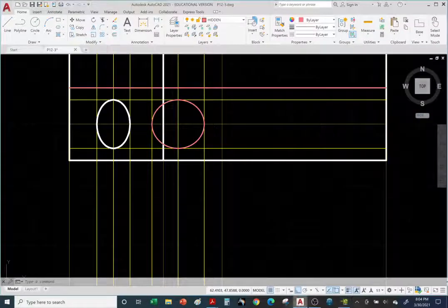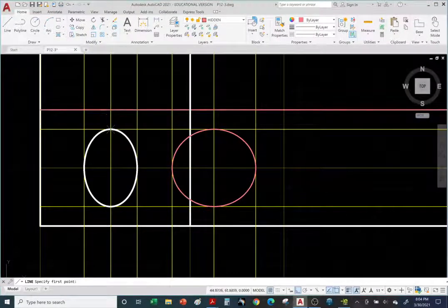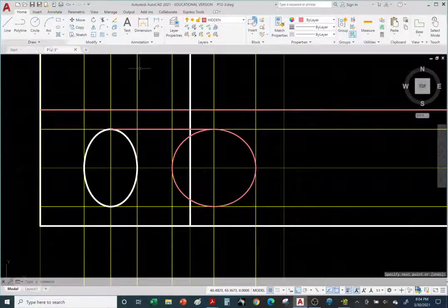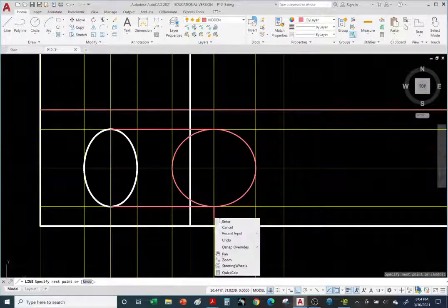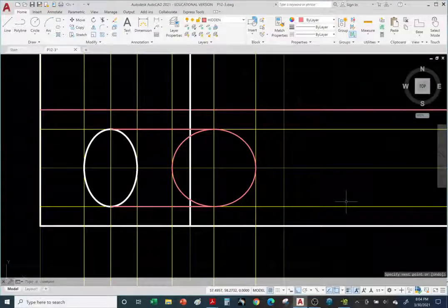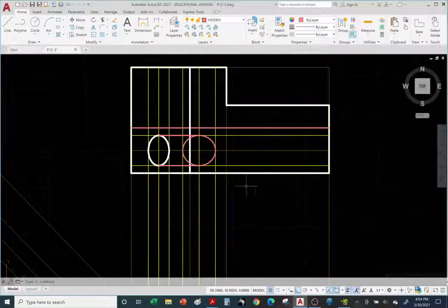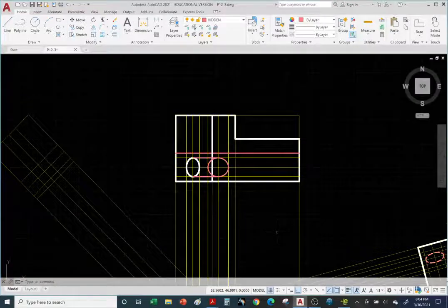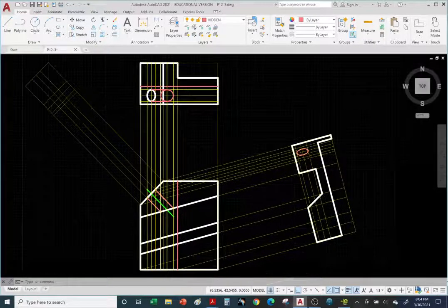All right, back to AutoCAD. Let's connect the ellipses with red hidden lines. They're hidden because we can't see them. Right-click Enter. Okay, and bottom quadrant, and right-click Enter, and there we have it. Ta-da! Done. All right, so let's cheat and take a look at the answer key before we move on to the auxiliary view on the right. I think we have everything so far.